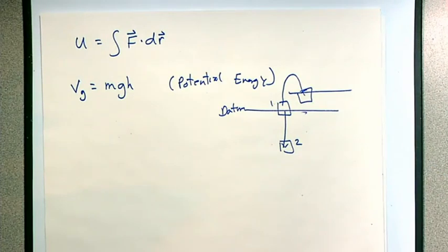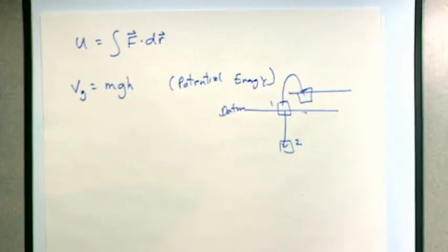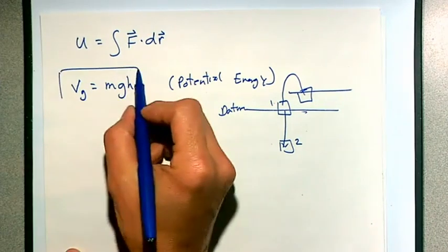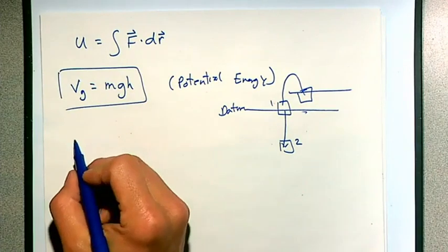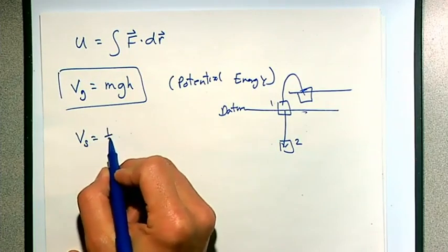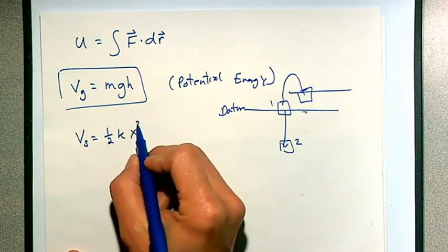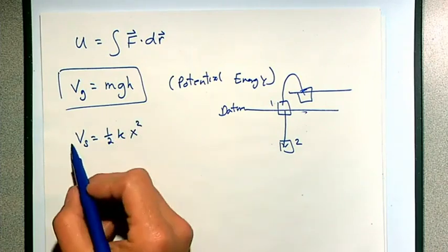The only gotcha is that before we just said mgh. Now this h, we have to track the CG location of our body. Because we might have a rigid body that can rotate, like this blob that we're showing in the figure here. Hey, it can spin all at once, but as long as I know how high up and down the center of gravity moved, that's all I got to do for potential energy. So this term, unchanged. Springs, still the same, half kx squared.